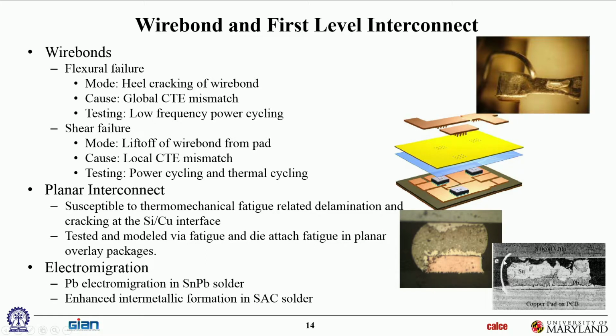Electromigration, you're talking about very, very high current densities traditionally. That's why your conductors are so thick. But even with such thick conductors, you're sometimes pushing the limits of the design and current densities are so high that we do see electromigration. Not just in conductors, where we see more often are in the solder joints. Believe it or not, there's electromigration even in solder joints.